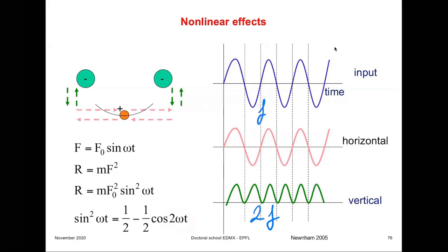And that's what electrostriction would do. Piezoelectric effect would go up, down, then change direction, go maximum negative, go back to 0, while electrostrictive will always go either only positive or only negative, depending on whether this coefficient M is positive or negative.